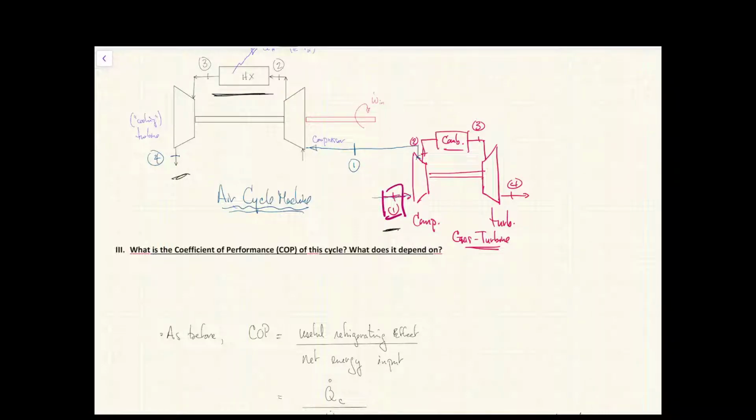And we're going to talk about dew point in the coming weeks. But what that means is the temperature at which the water starts to condense. And you know this, right? Dew on the grass in the morning on a humid night is significant, and that's because the grass and the ground is colder than what the air can sustain locally as a water vapor. So the same is going to happen in the turbine, the cooling turbine, and you're going to be spewing water out of that side of it.